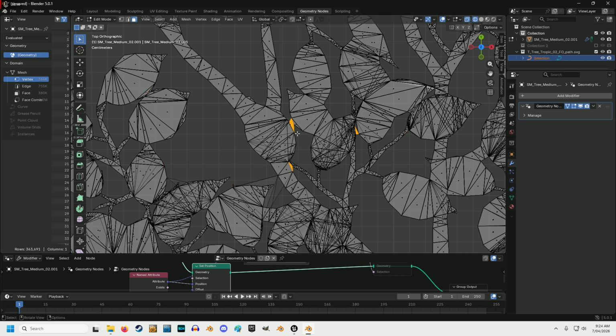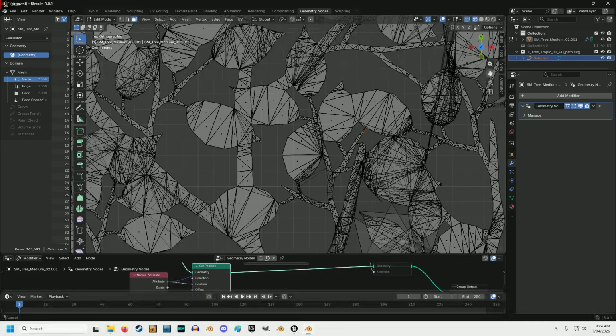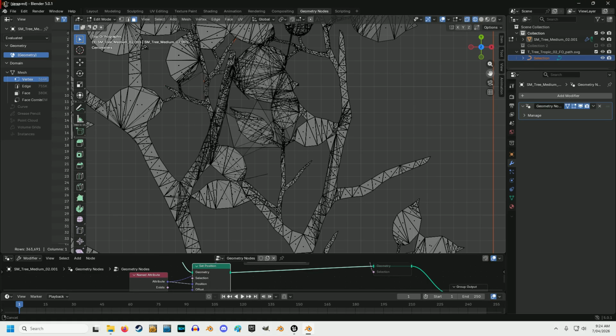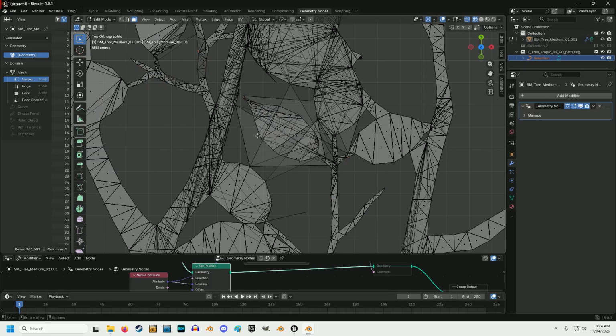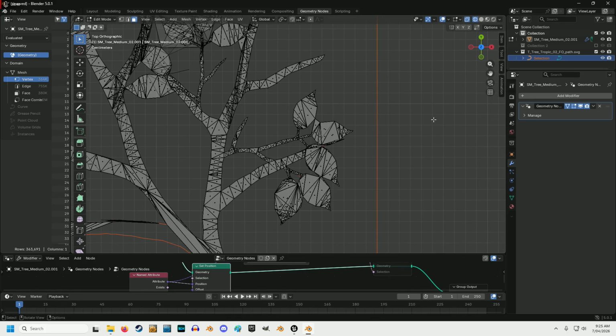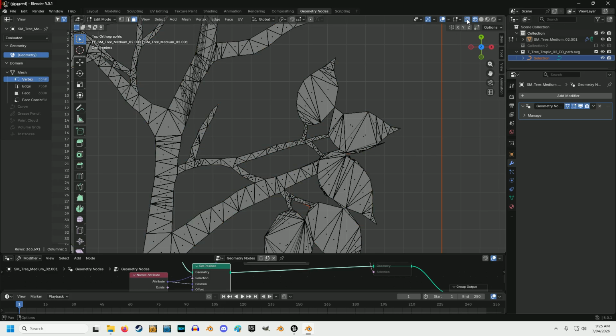Anything you don't select and then delete faces will cop a little bit of black or no texture in game, so just bear that in mind. If it's a big slab like some of these ones in here, they will probably show up in game and it'll look not great. So go around and turn this on and off, find your polys that you want to delete, and delete all of those. I'm going to leave some in that I'm not too concerned about.